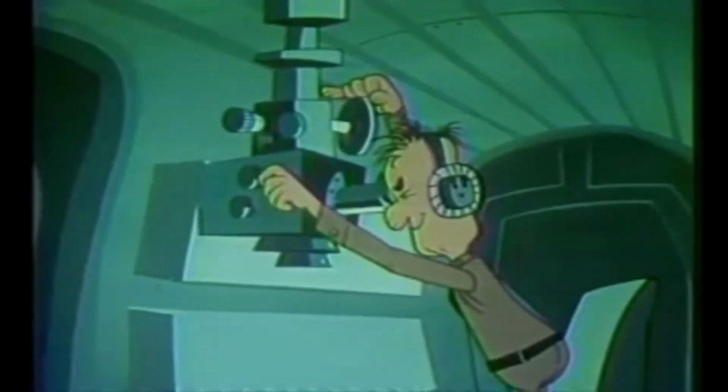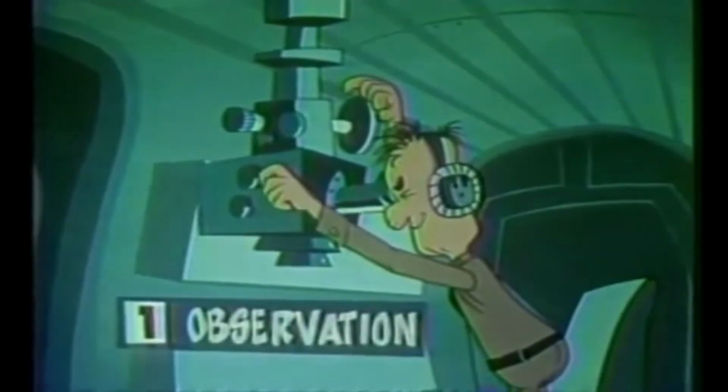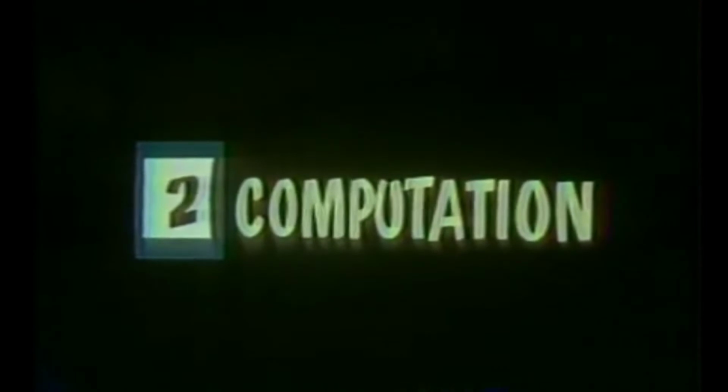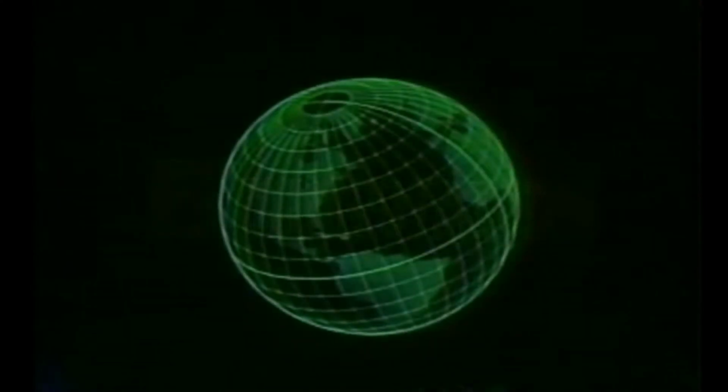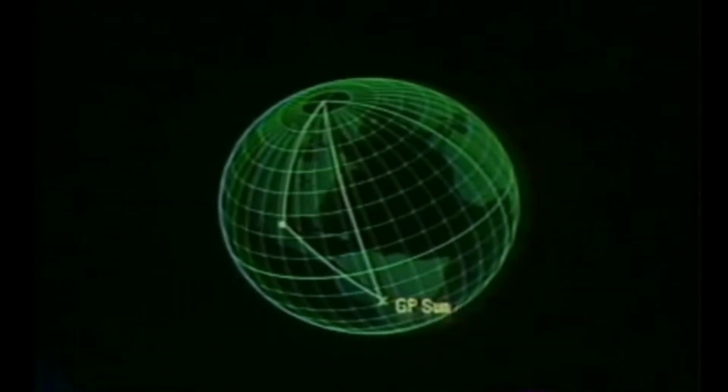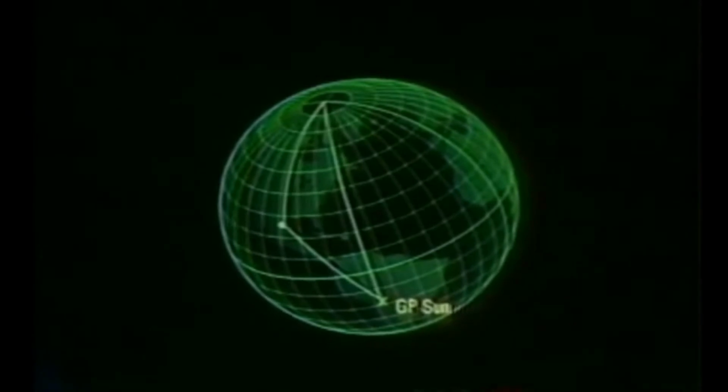Let's review the key points briefly once more. It all begins with an observation of a celestial body to determine an observed altitude, HO. Then comes computation. The mathematics of the intercept method involve the solution of a celestial triangle brought down to Earth. The points are the GP of an observed celestial body, an assumed position near your DR, and the pole of the hemisphere you are operating in.